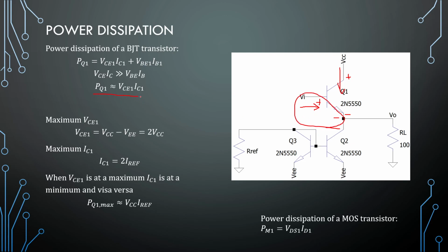So the power of a transistor is approximated to be VCE times IC of a transistor. Okay, calculating the power dissipation over a power transistor is very important, especially when you need to choose one, so that you don't burn out the transistor or overload it and poof, gone output stage. Some of these transistors can be quite expensive. Okay, so always do the power calculation of your components.